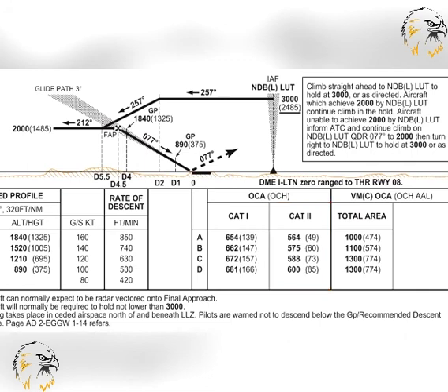Wingspan is not more than 60 meters, and the vertical distance between wheels and glide path is no more than 6 meters. Missed approach climb gradient is 2.5%, and the glide path angle is a minimum of 2.5 degrees, has an optimum of 3 degrees, and a maximum of 3.5 degrees.